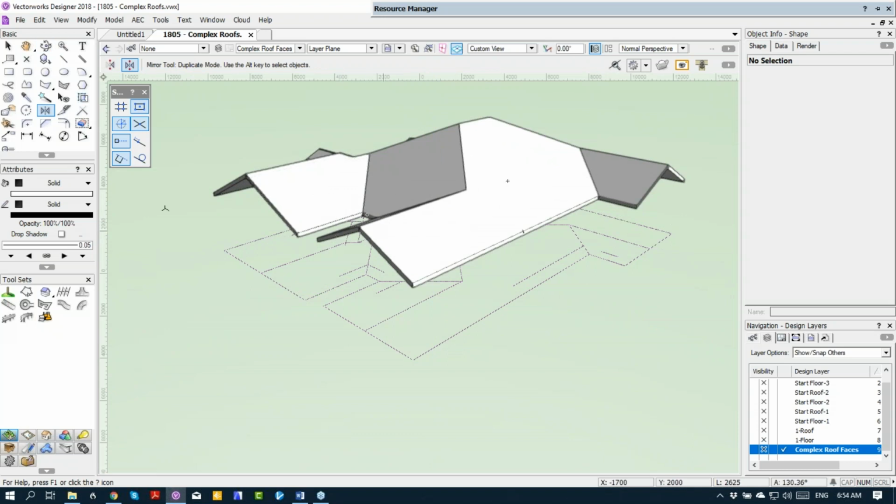You could use the Connect Combine tool. You can use that to join roofs together. When you're doing your mansard roof, James, wasn't it? The mansard roof, James, you might want to use this mode here to join the two parts, because otherwise you'll find that the roofs don't join neatly. Otherwise they have this funny vertical cut. This one here does a really cool job of joining them together.